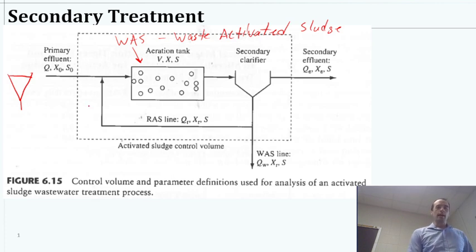Okay, so once we've done that, we send it to the bacteria to eat a bunch of stuff. We oxygenate it, really trying to drive down the BOD by letting the bacteria grow on the stuff. So they're essentially removing BOD by demanding oxygen that we're giving to them. Then we have the secondary clarifier, which is going to serve as a way to collect just about all of our bacteria. And in terms of the scale of bacteria in these systems, it is actually close to all of it, if we're talking about grams per liter of bacterial mass. A tiny bit slips away and through, and it's enough that we have to disinfect and everything. We're definitely not going to get everything, but on a mass basis, it's pretty close.